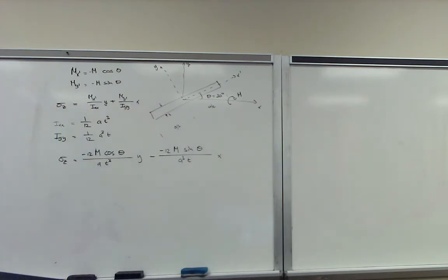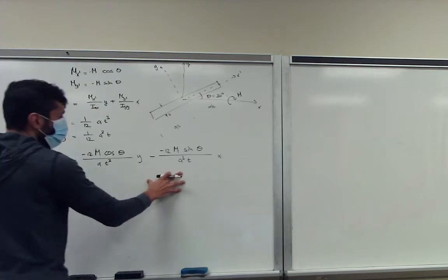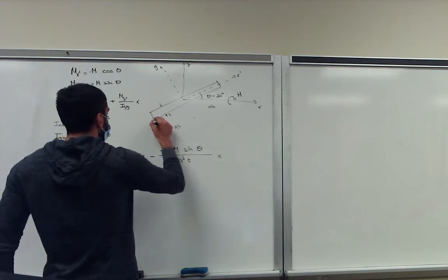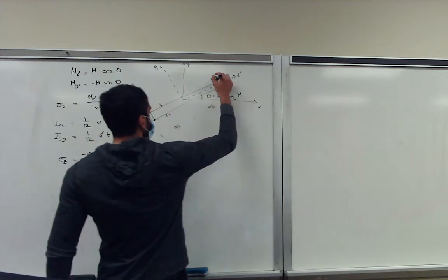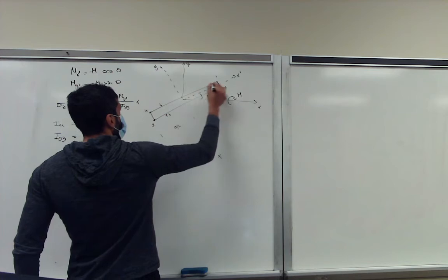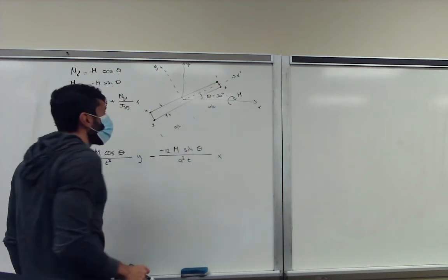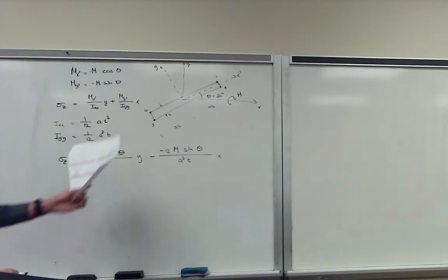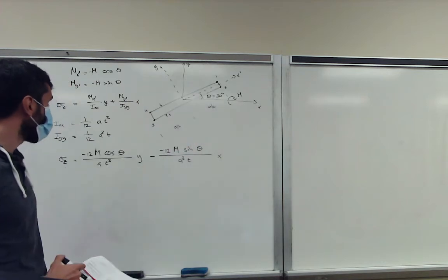Now we can plug in our values for x and y, and we have 4 coordinates that are of interest to us. Let's call these 1, 2, 3, and 4. At those locations either x or y are positive or maximum, so if we want to determine our maximum stresses, it will occur at one of those 4 locations.